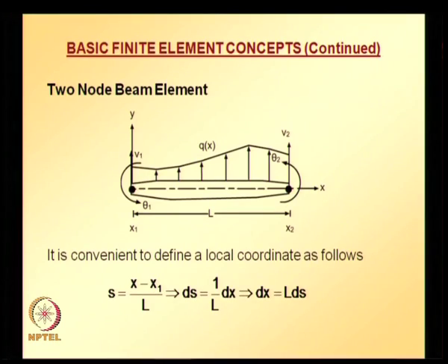Once we got this relation, we can find how a small differential element of length ds in the s coordinate system is related to a differential element of length dx in the x coordinate system, that is given by ds is equal to 1 over L dx, and that can be rearranged as dx is equal to L times ds.